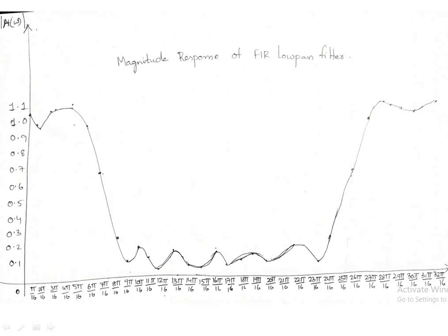In addition to these design problems, I would also like to add some more points related to the windowing method and frequency sampling method. Generally, FIR filter design by using the windowing method and frequency sampling method suffers from a little drawback, that they don't have any kind of precise control over the critical frequencies such as the passband frequency and the stopband frequencies mentioned in the design problem. This drawback can be overcome only by designing FIR filters using optimal equiripple design criteria or Chebyshev approximation techniques. In those techniques, an error function will be used to approximate the ideal frequency responses in order to satisfy all those desired specifications that we require.